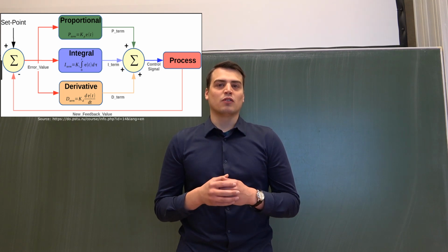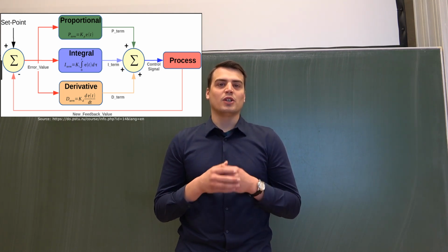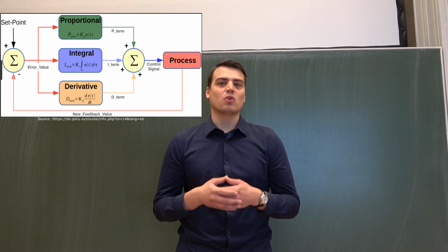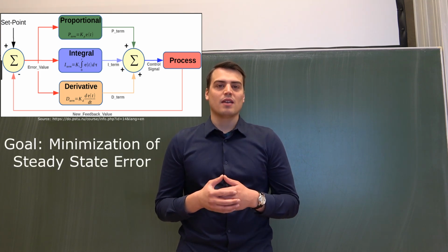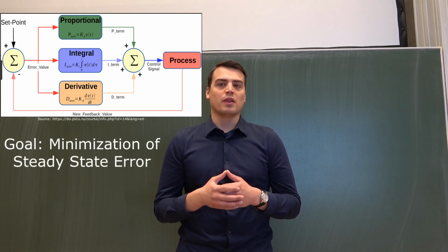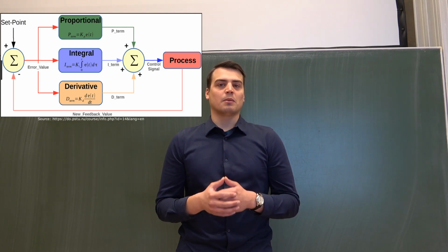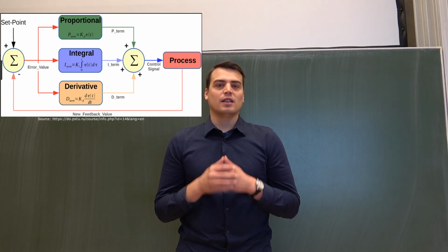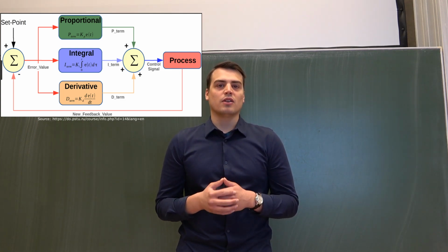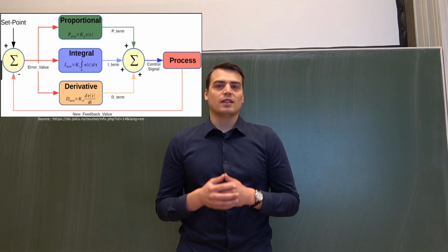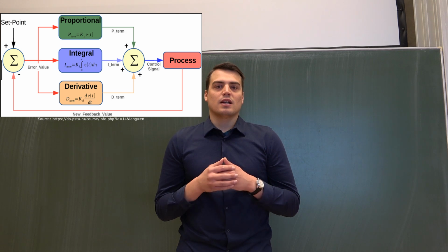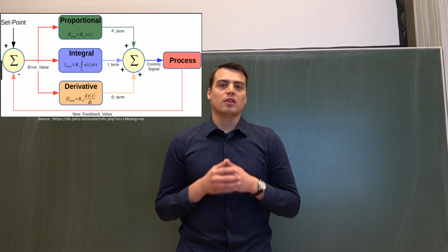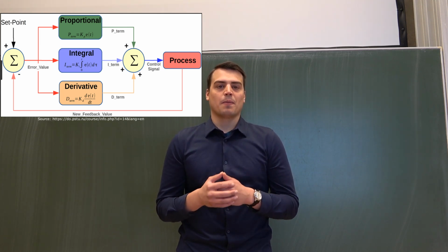The second component of the PID controller is the integral part, which sums up the error over time. Its main purpose is to bring the so-called steady-state error to zero. However, a significant issue with the integral part is the integral wind-up phenomenon. This occurs when the set point changes rapidly, causing the integral part to accumulate a significant error during the rise period. This effect is a major problem, and there are anti-wind-up techniques available which are not relevant now, but can be explored further if you're interested.